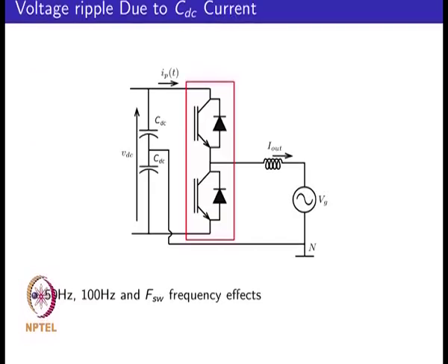Essentially what we had done was we calculated the current components, then we looked at what the thermal impedance from core to ambient is, and we looked at the values of ESR at different frequencies and calculated the temperature. So, we got 4.6 years and the loss in the capacitor ESR because of these various current components totaled, in both the top bank plus the bottom bank, each bank consisting of 4 parallel capacitors, to be 15 watts.